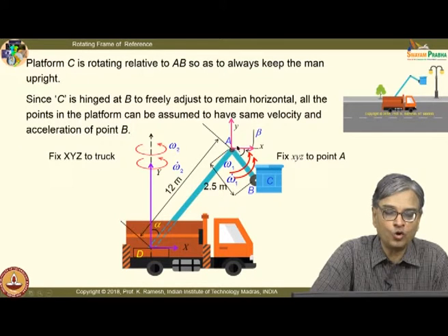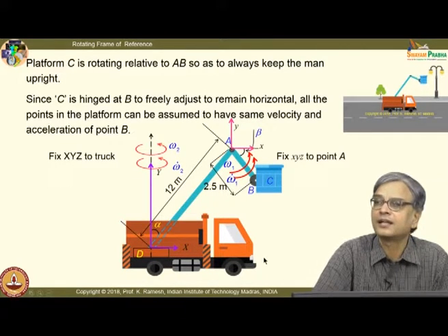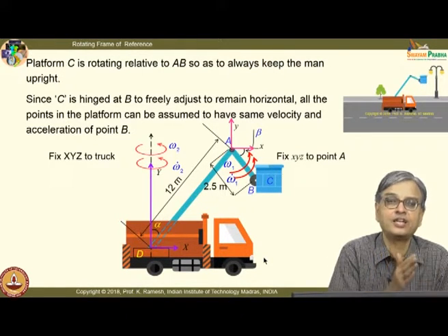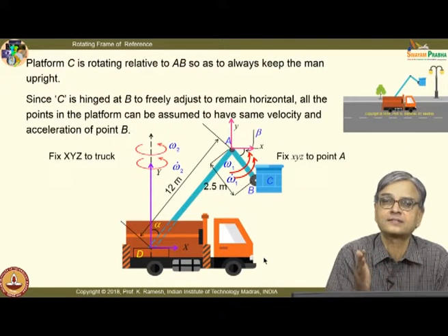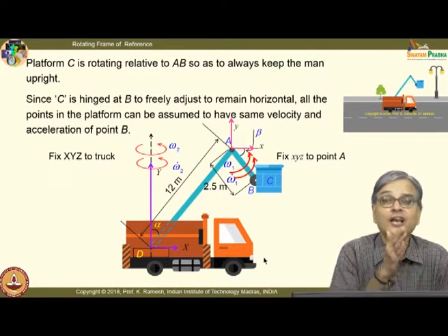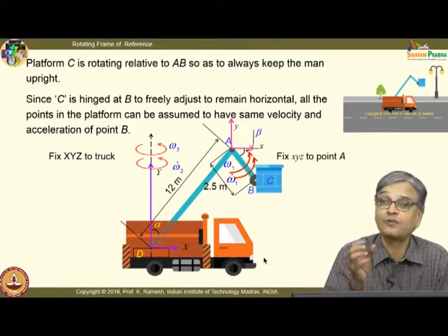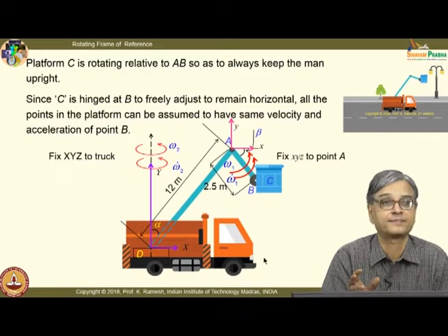With this choice, I have no confusion of capital I and J and small i and j, they are parallel. So, I have no difficulty in handling the expression, because when I say VA equal to VB plus omega cross R plus VREL, they are all referred to different coordinate systems in a generic problem. So, you have to use the vectors properly.